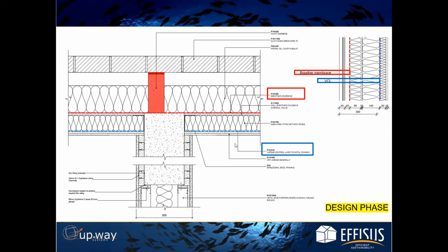And what we do is that we work together with facade consultants and architects, and then with them we develop solutions that are going to be perfectly fit for the projects that they are working on. And so here, some of the things that we do is like where to place exactly the breather membrane, the VCL membrane, what is the best possible position and where to place it.